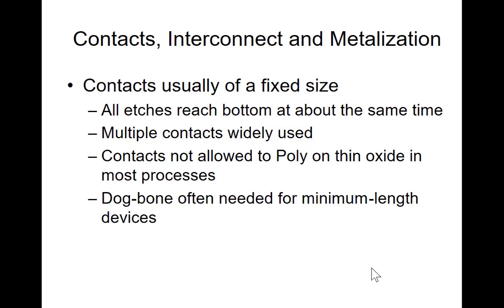Now also we said that for this transistor, this is the critical area that forms your transistor. And you never want to put any contacts right on top of the transistor, because that's the most critical place. You don't want to put your contacts right on top of the poly to connect to metal 1.